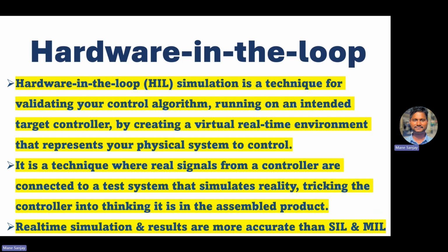The main goal of HIL testing is to verify the correct operation of the embedded software in the target processor and its surrounding components and the environment. The correct operation of the embedded software in the target processor means whatever software we have flashed into the ECU, we have to check its correct operations. Its surrounding components means whatever sensors are connected to that ECU.